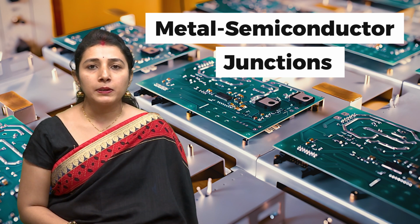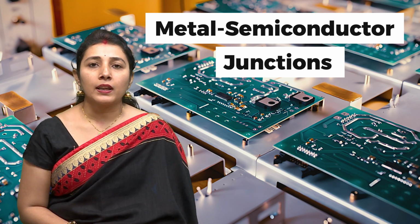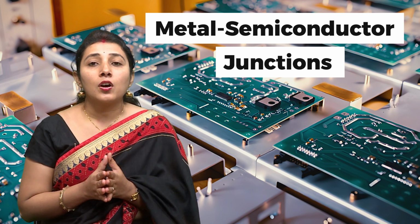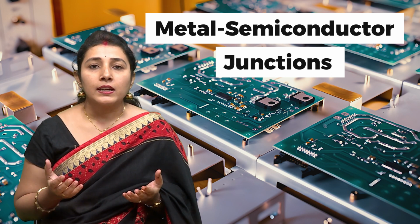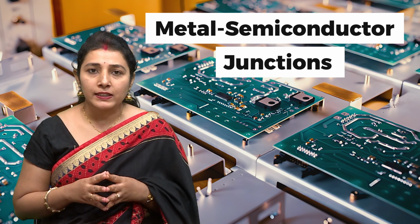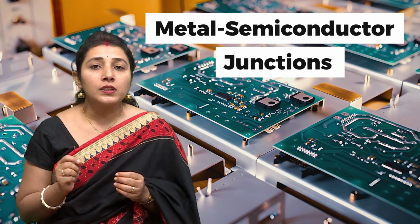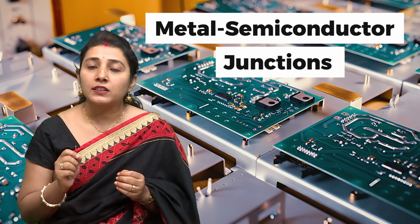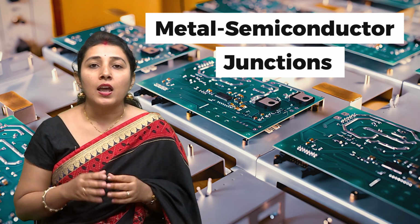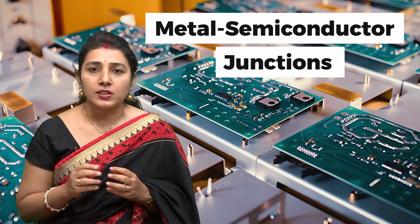Many of the useful properties of a p-n junction can be achieved simply by forming an appropriate metal semiconductor contact. This approach is obviously attractive because of its simplicity of fabrication, and also, as we shall see in this section, metal semiconductor junctions are particularly useful when high speed rectification is required. High speed rectification is the major application where we use metal semiconductor junctions.